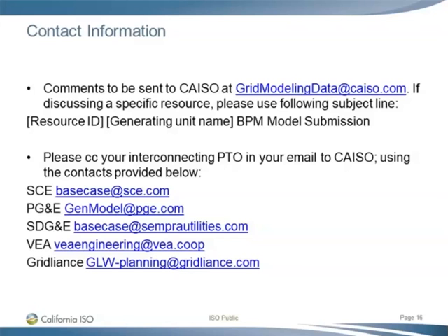There is no additional requirement for the synchronous generator. For synchronous generators, it has been decades that SSR could be a concern, so we require an EMT model for synchronous generators if they are close to a series compensated line. Not every synchronous generator is required to provide an EMT model, only if it is close enough to a series compensated line and could be a concern for subsynchronous resonance. So this requirement has always been there. We didn't change this part.